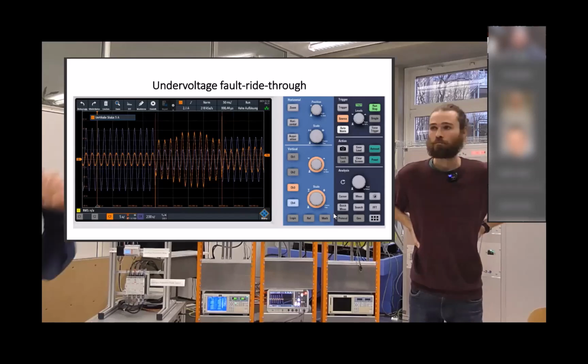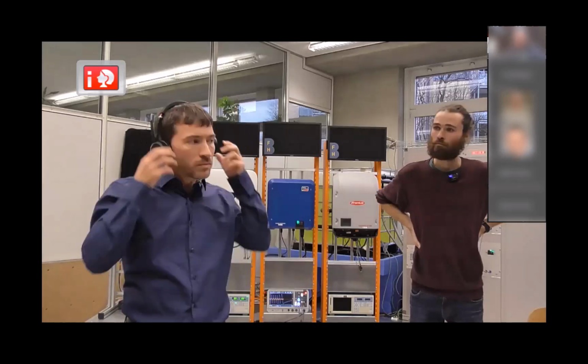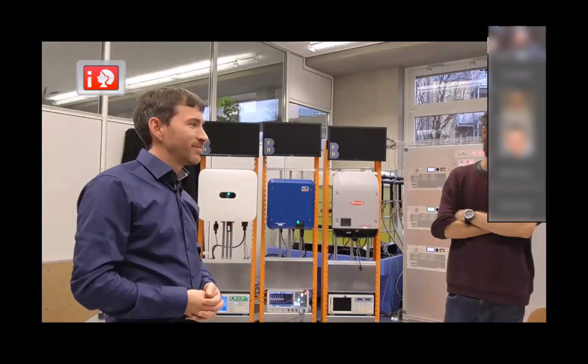Yes, I understand. My question was regarding the transient peak. So what was the maximum current transient peak at the time when the fault appears? It is actually the current control, and when we see such a disconnection of the conductor, it's a behavior of the capacitance in front of the PCE, and you can see such a transient, but it doesn't cause any problem to the PCE at a very low level.